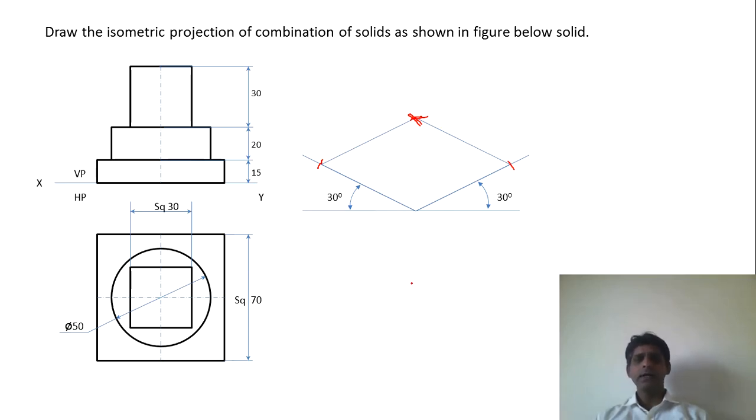The isometric view. Again, let me mention that whenever we are doing it in the software, we will draw the view first, and then all of the lengths will be converted to isometric lengths by multiplying all of them by a factor of 0.81649.